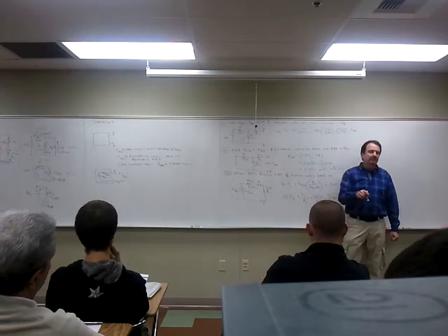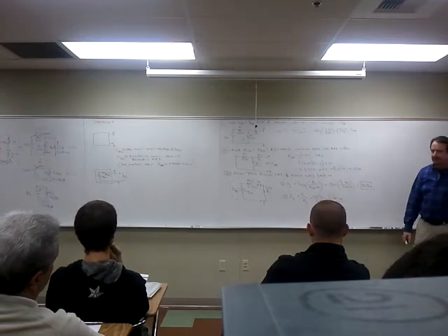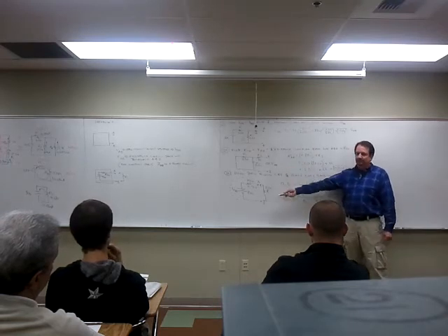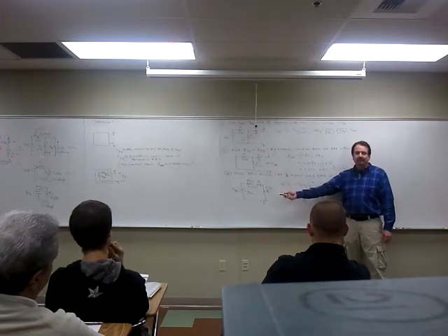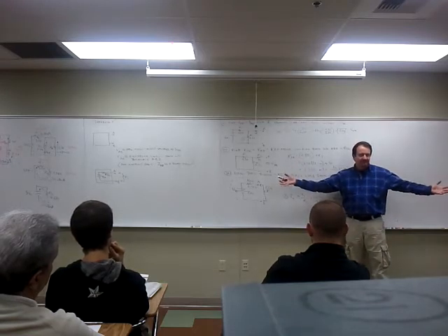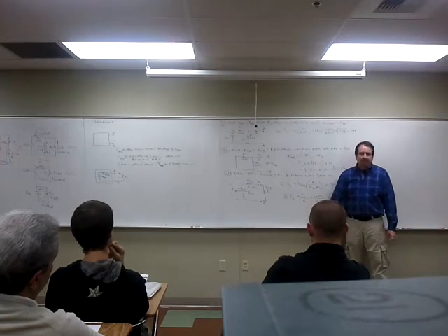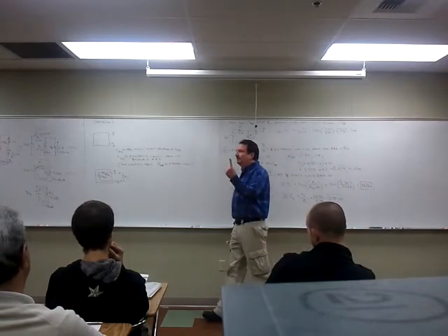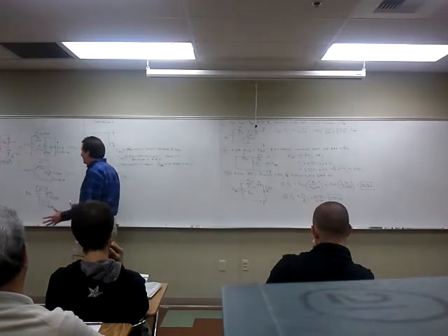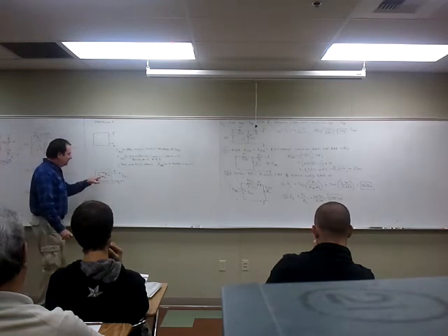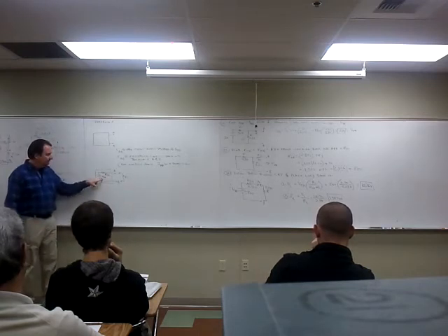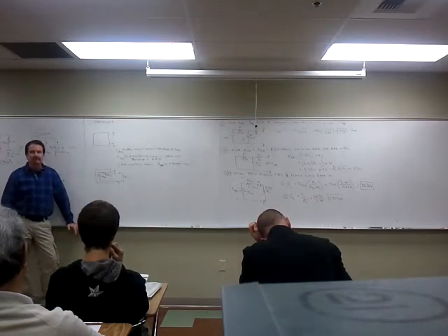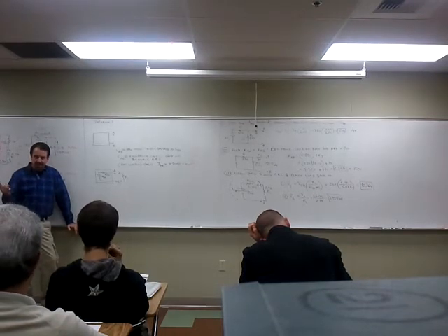So even if you're programming a computer, what is better? What if it's a complex system and you're programming a computer? If you program the computer to use an equivalent circuit, the computer would be 30 times, 100 times, 1,000 times faster, depending on how many changes you make to the circuit. So one reason for doing Thevenin's equivalent is to take a complex circuit and reduce it to this equivalent circuit of a voltage source and series resistor. Then as you change that load, it's simply 2 calculations to find the voltage and the current. That's one reason.